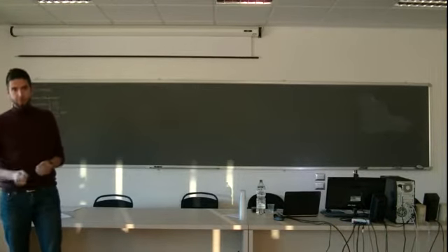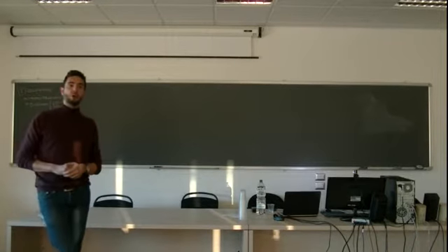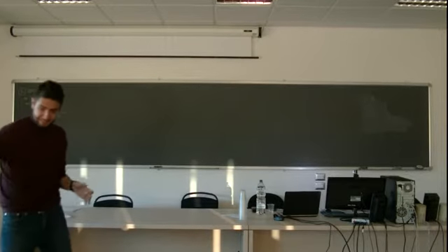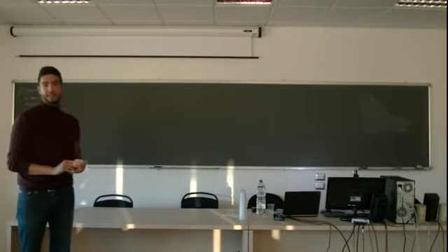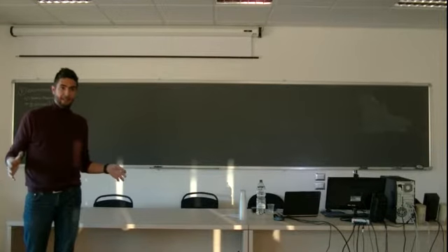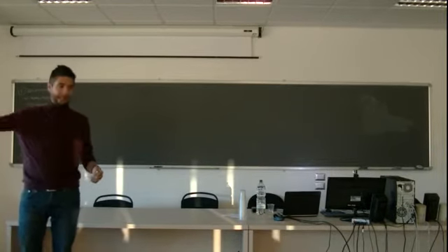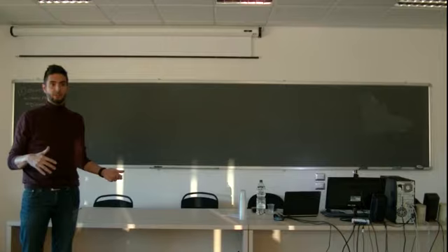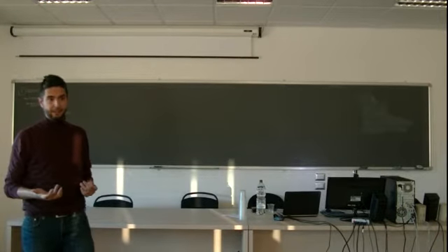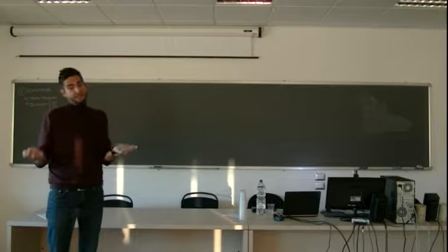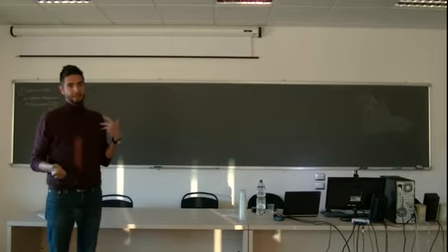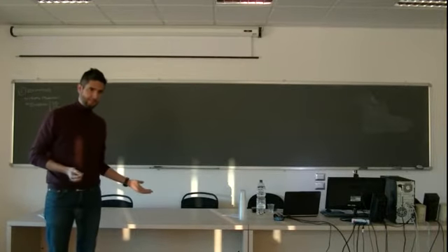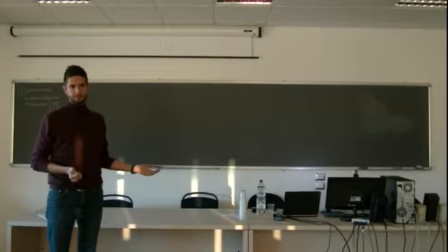Surface temperature of the floor, because you have, I don't know, a pavement or whatever, or room temperature. Is room temperature very sensitive if the sun is just in this region or in another region? Can I assume 1D, and if the solar radiation is just facing half of the room, just compute half solar radiation? Is this assumable or not? Try to do tricks on that. And try to be engineering in this sense. So if I am adding complexity, it's because it deserves it. Otherwise, keep the complexity for CFD.